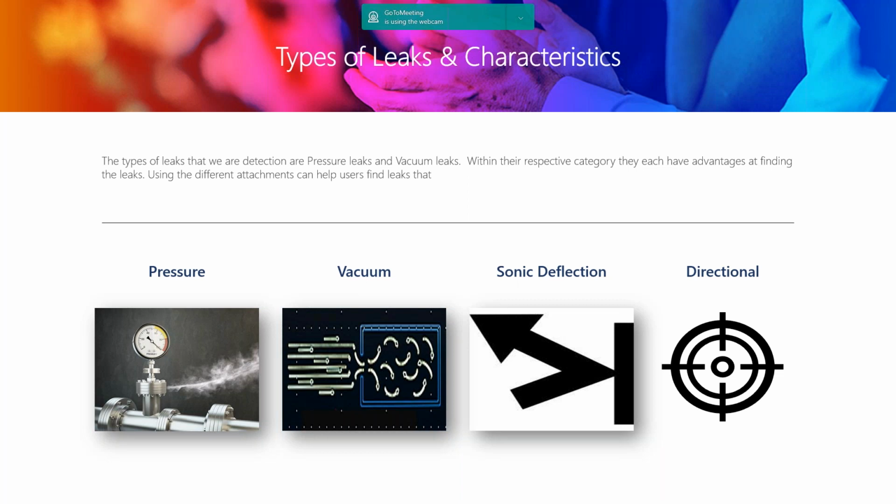Wherever you point that piece of equipment, say at a leak, it's going to instantly let you know whether you're close or not. With that, honing in with some of the other modules to find pressure leaks or even a vacuum leak, I mentioned the close focusing module. That's more for when you're in an already quiet area and you're trying to find an itsy bitsy teeny tiny compressed air leak or vacuum leak. And then we've got what's called a long range module that can get you out to say 80 to 100 feet, good for rafters, overhead piping, that sort of thing.